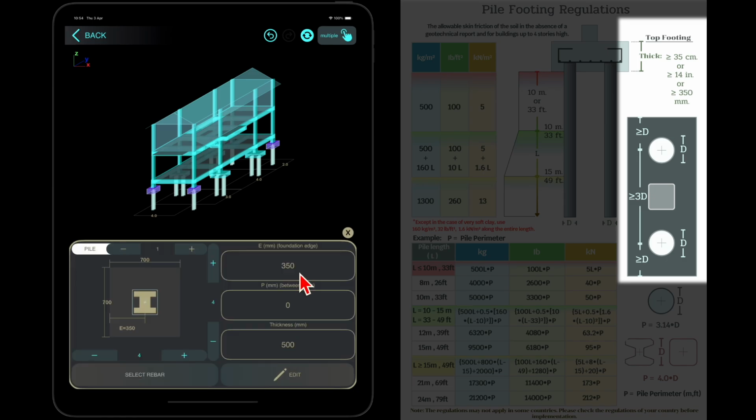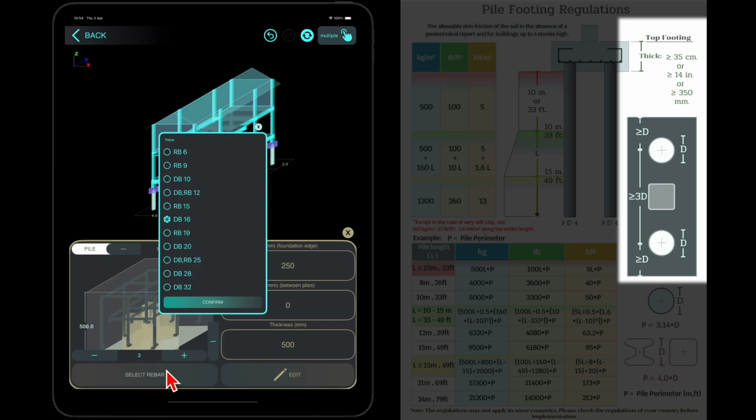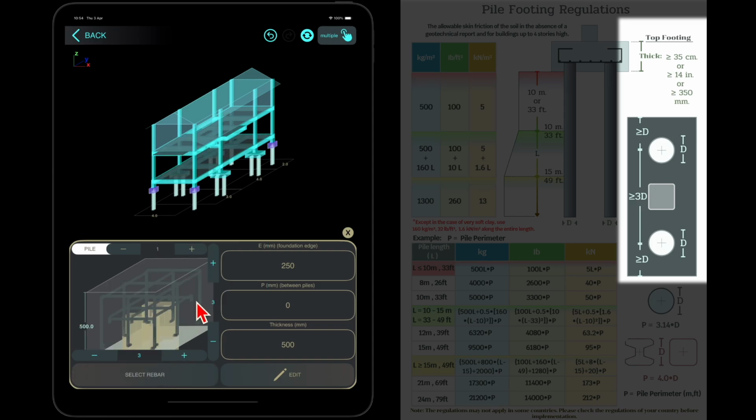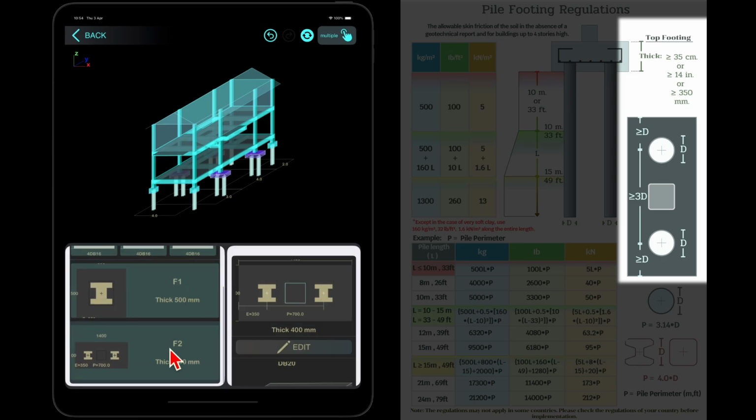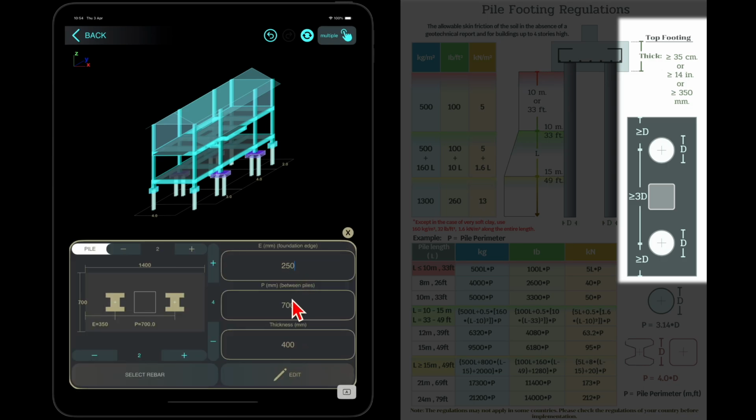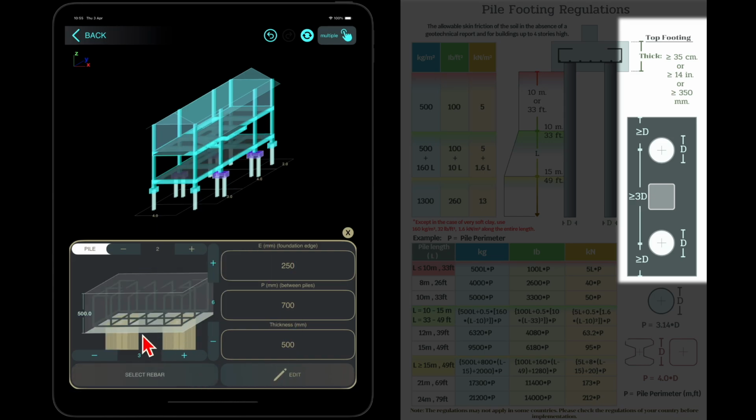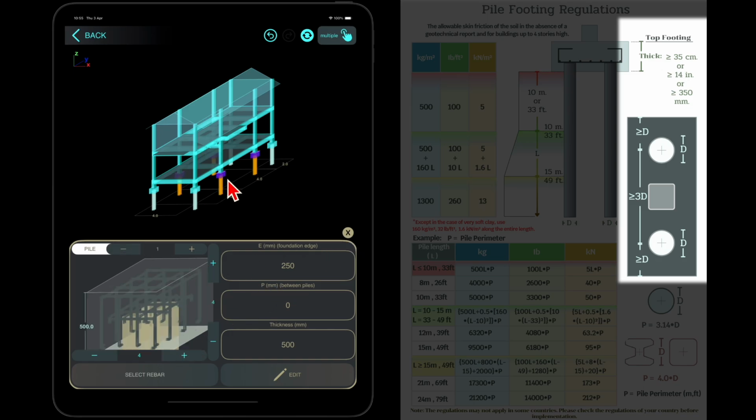Foundation design considerations. We can reduce the foundation size according to engineering standards. If the system-generated rebar quantity is insufficient, users can manually add more reinforcement. The number of piles can also be adjusted as needed. If the design fails, a warning color will be shown on the model.